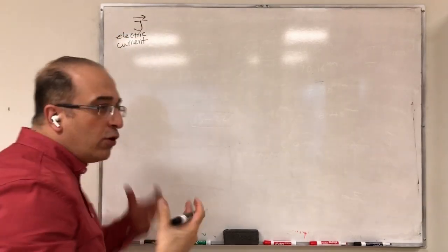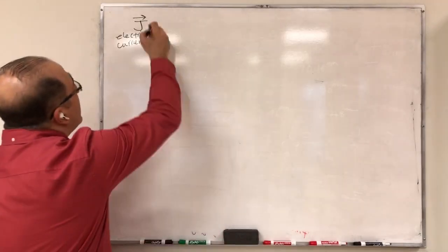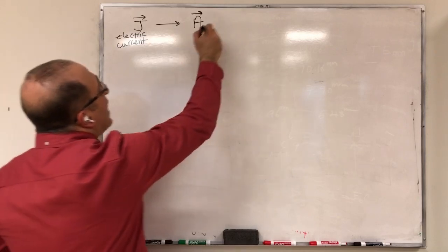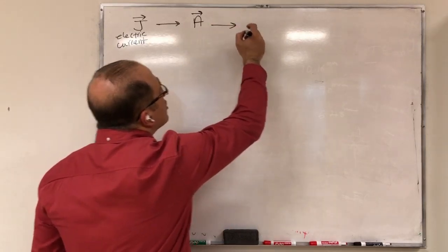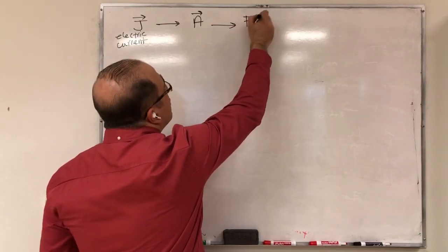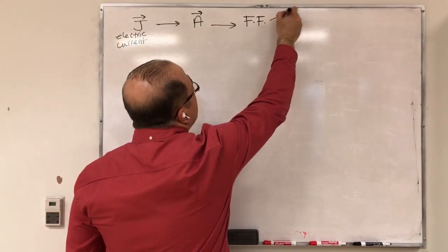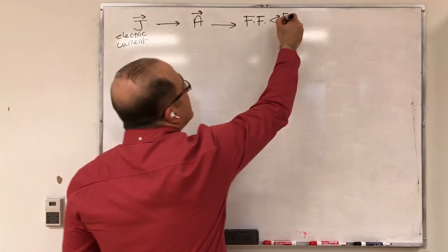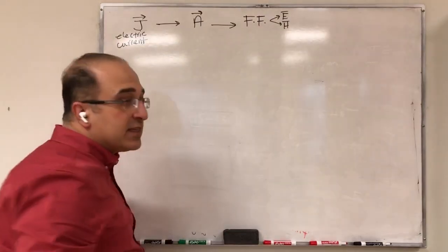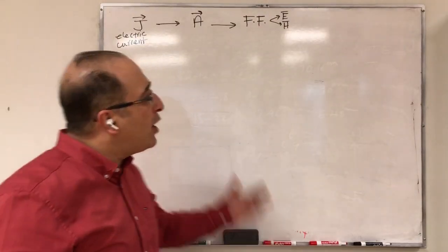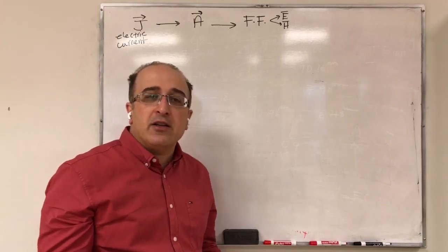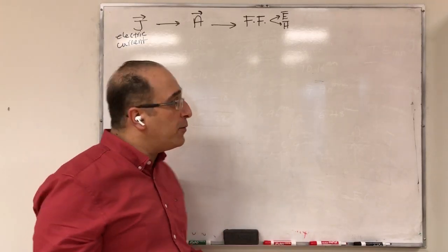If you know what is your J, then we find magnetic vector potential. And from magnetic vector potential, we can find far field E and H. So this is one way that we discussed in the course. We applied this, for example, in the case of dipoles because we know the electric current of the dipole on the wires of the dipole.